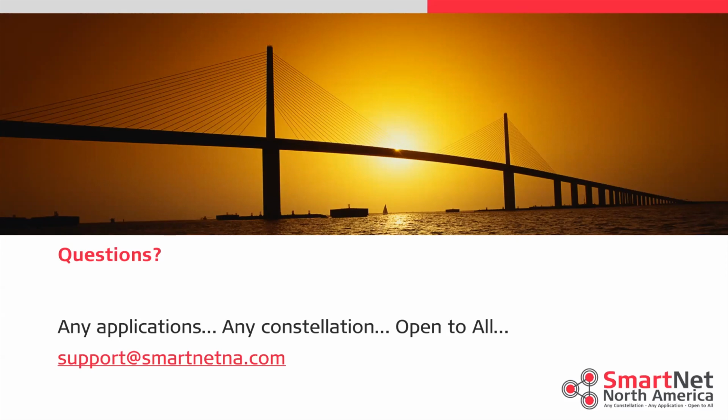To clarify, you will be able to upload the new mount points' broadcast coordinates into the survey controller before they become available for production? Okay, so you don't actually upload broadcast coordinates into your controller. We broadcast those in the actual correction. So when you connect into the network, one of the components of the message that we send out are the broadcast coordinates of the station that you're getting a correction from.